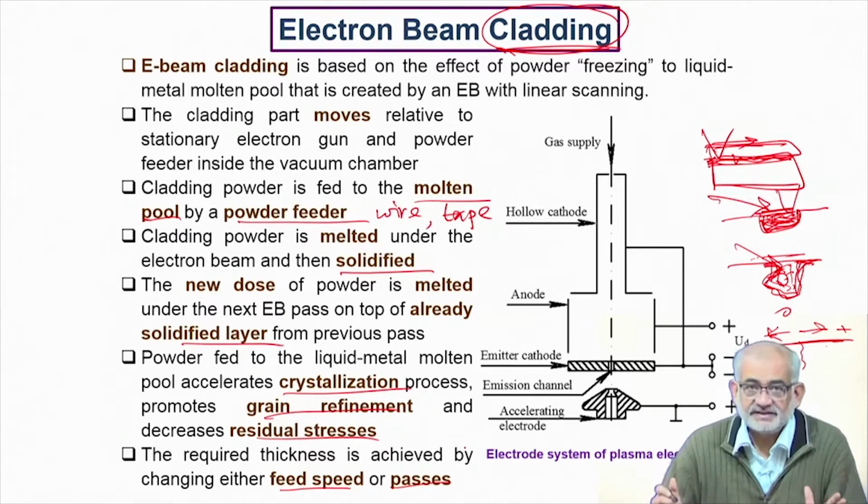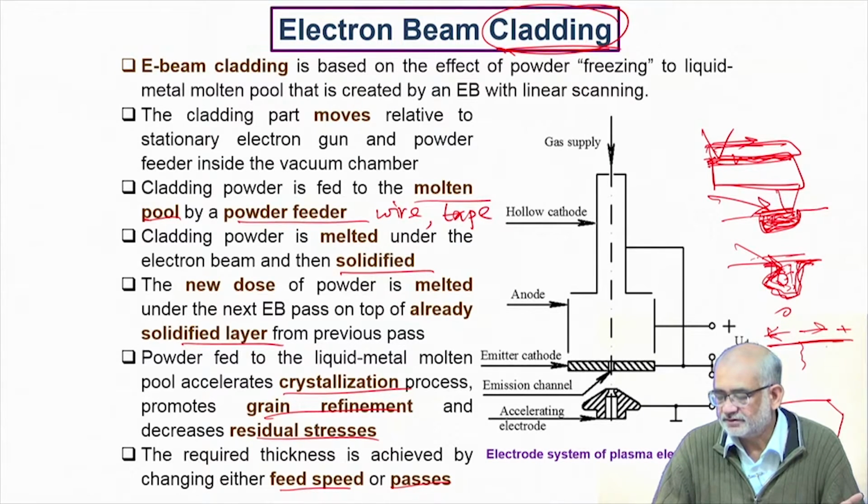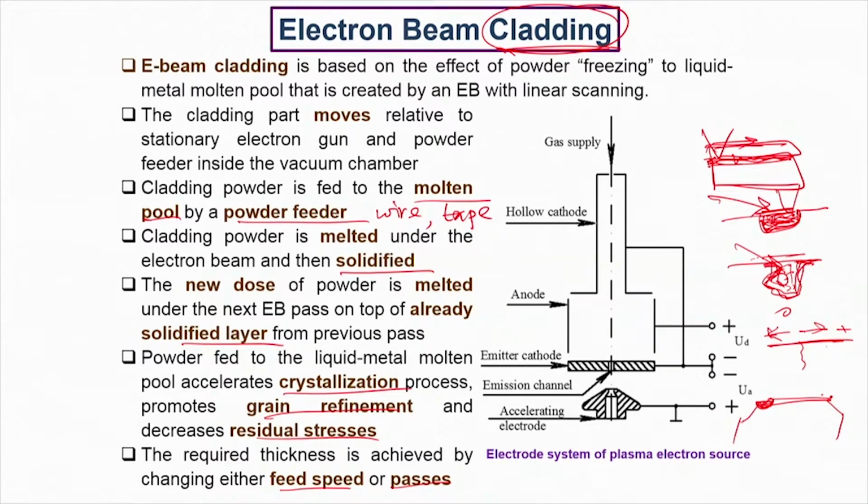I mean, clad essentially would mean as if you are cladding the whole surface, then you call it cladding. But when you are repairing only a small part of, let's say, a particular shear blade, so this is the shear blade which actually got worn out, so you are treating only this part. So this is refurbishment, this is reclamation. Whereas if you want to put a hardened layer on throughout the surface, you call it a cladding process.